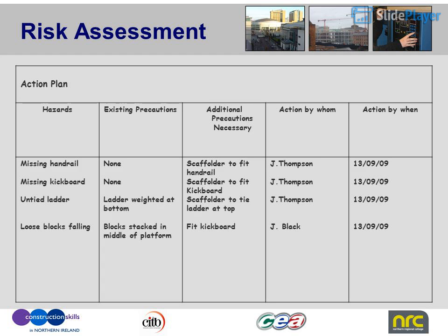Additional precautions necessary. Risk assessment action plan. Hazards. Existing precautions. Additional precautions necessary. Action by whom? Action by when? Missing handrail. Missing kickboard. Untied ladder. Loose blocks falling. None. Ladder weighted at bottom. Blocks stacked in middle of platform. Scaffolder to fit handrail and kickboard. Scaffolder to tie ladder at top. Fit kickboard: J. Thompson. J. Black. The 13th of September 2009.